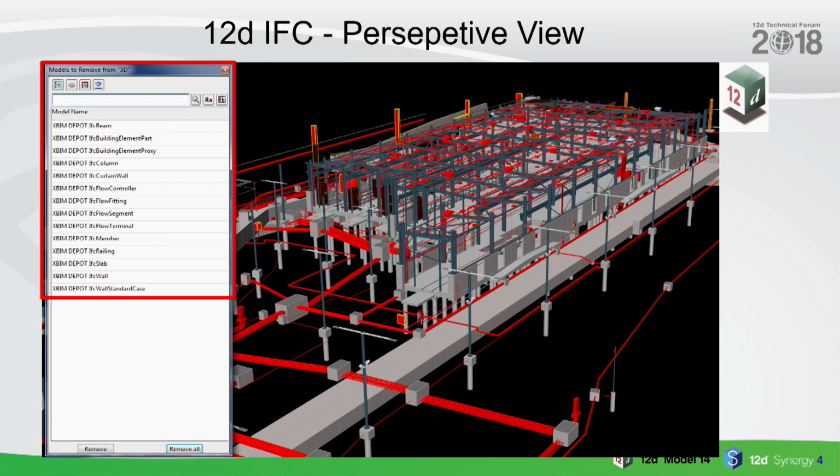There's a few benefits to this, in that sometimes in Revit, if we don't set our export options separately, we can actually bring in voids that we've used to cut walls and floors, and you can't actually turn them off very easily if you're bringing in one sole model.